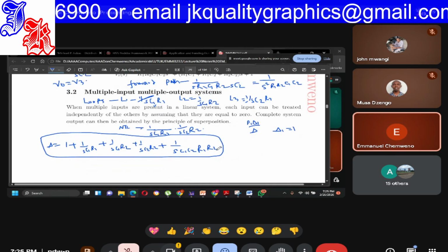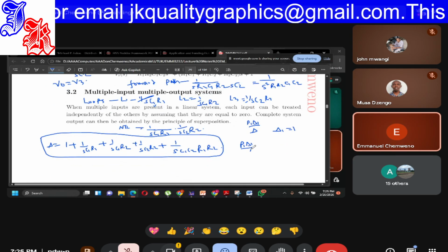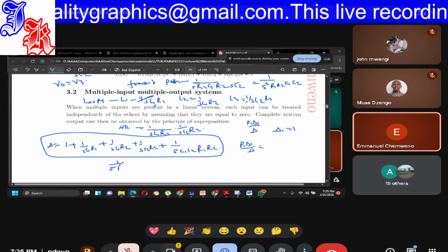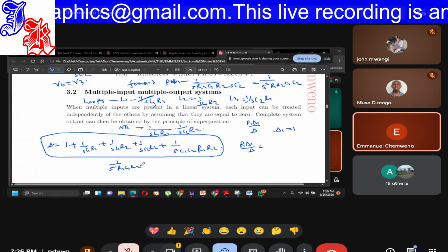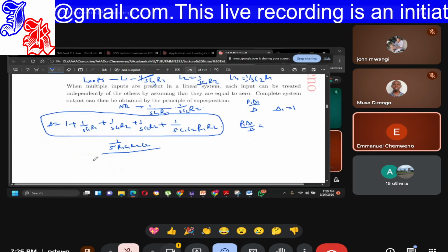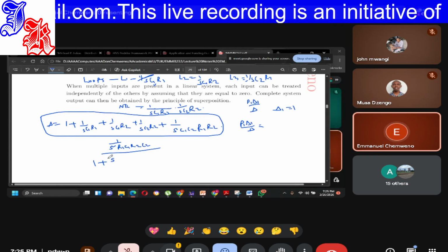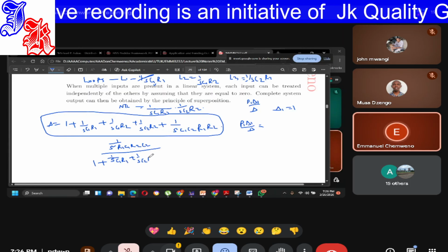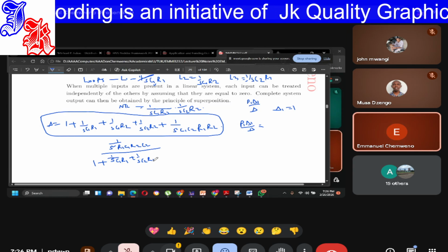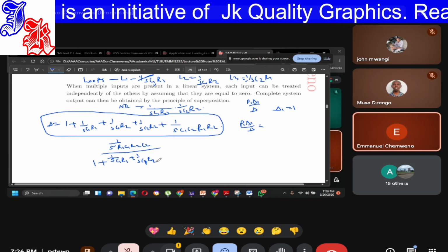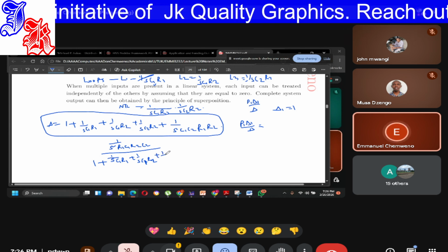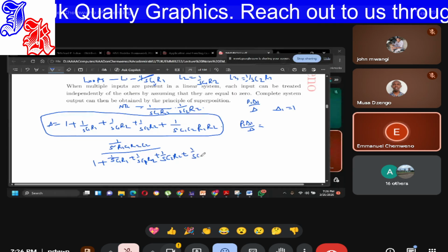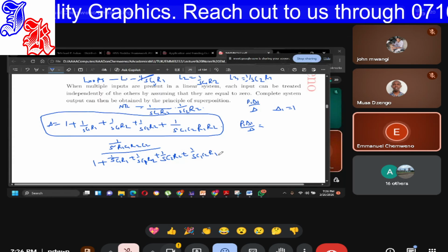Therefore, P1 cofactor 1 over determinant is equal to the forward path, 1 over S squared R1 C1 R2 C2, over 1 plus 1 over S C1 R1 plus 1 over S C1 R2 plus 1 over S C2 R2 plus 1 over S squared C1 C2 R1 R2.